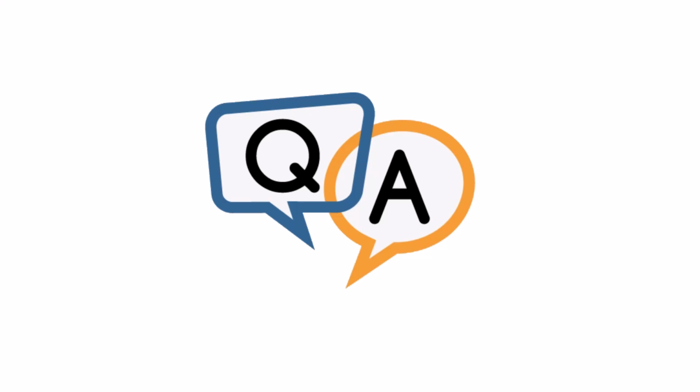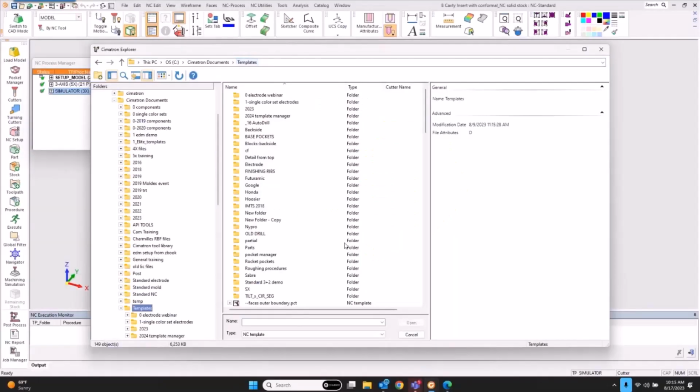Another one is here, copy and paste geometry transfer. Does copy and paste geometry still transfer boundary offsets? It's very annoying to add a roughing template at 0.01, then a finishing at 0, pick the geometry for the roughing one, copy and paste it to the finishing one, and have it also switch the offset to 0.01 plus. Let's find out. I'll go see if I can find an old template.